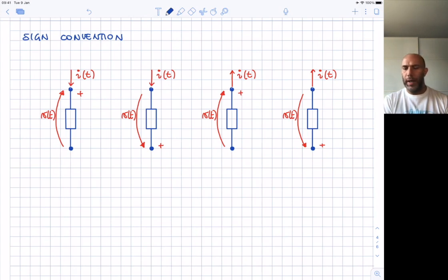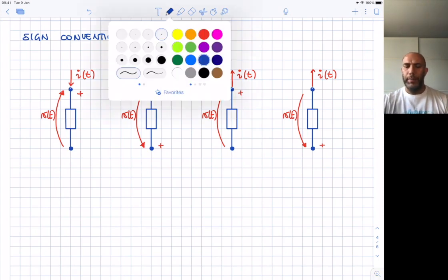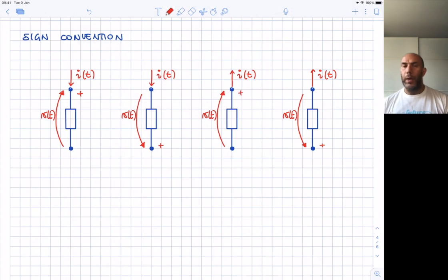And the same happens in the last component, because in the last component the current is flowing outside the top terminal, and so it is flowing inside the bottom terminal. And so if we refer to the combination of the directions of voltage and current, these two versions of the component are characterized by the same orientation of the combination voltage current. And we call this orientation the P orientation.